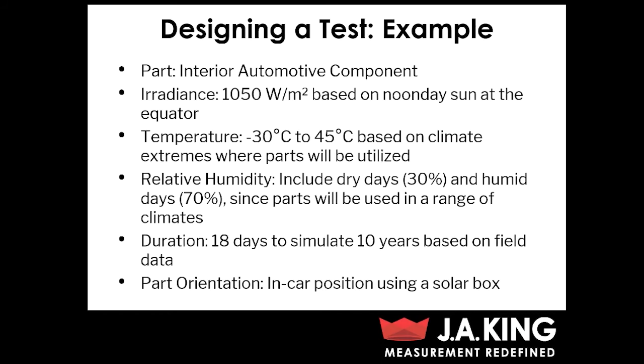So typically what you have to do is take some field data and use that to determine an appropriate duration by correlating the effects you see in your field data versus what you see during testing. So for this case, we're going to go ahead and say that we're going to test for 18 days, which for automotive components is actually quite standard to simulate 10 years of in-field usage.